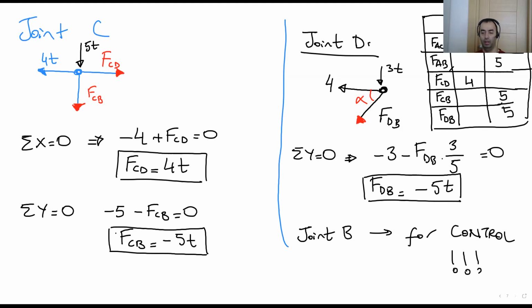After that, one by one, we take out the joints of this truss system and write equilibrium equations. When we take these joints out, if we know any forces acting on this joint, we write them there with their sign. If we don't know an internal force, we make an assumption. We always assume they're tension.